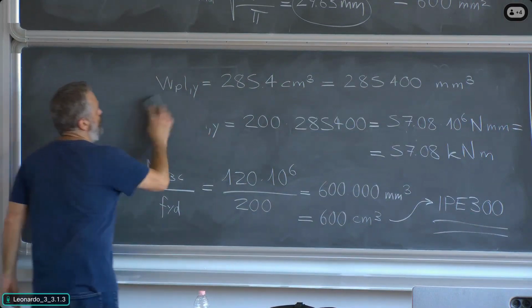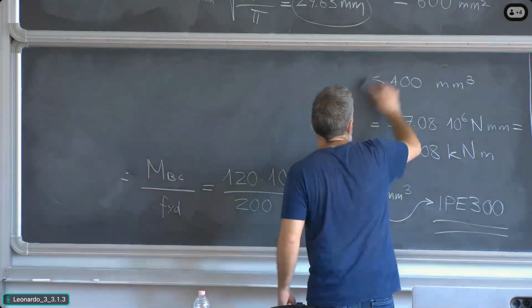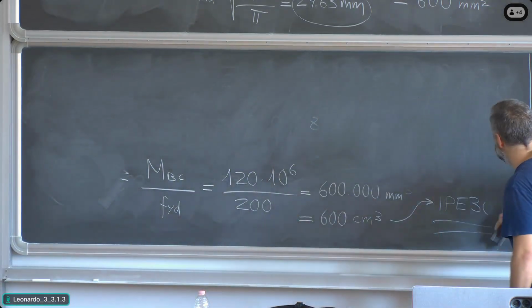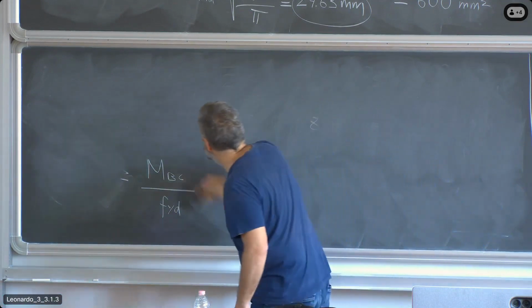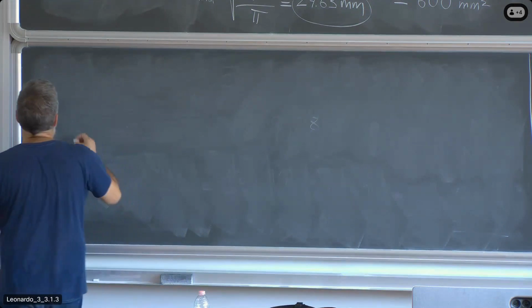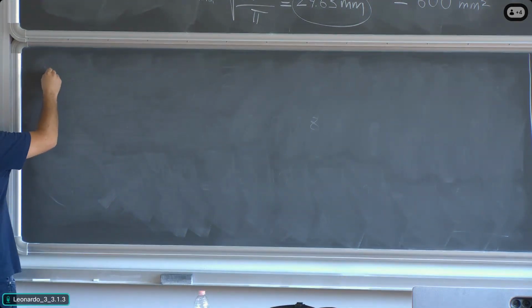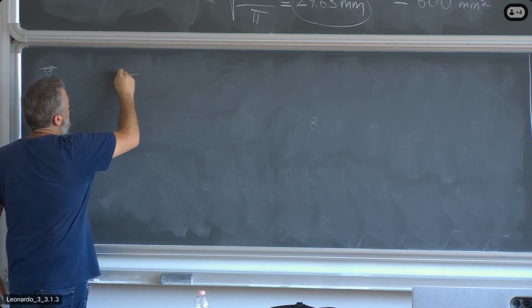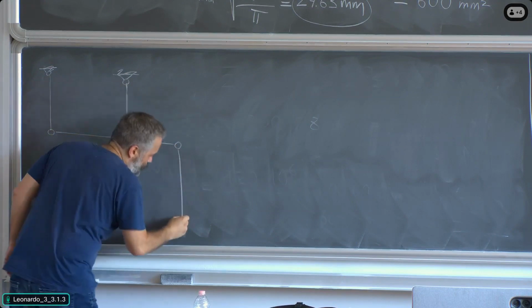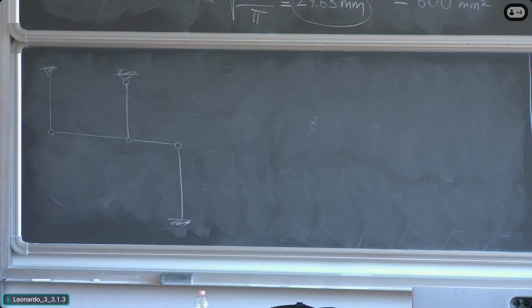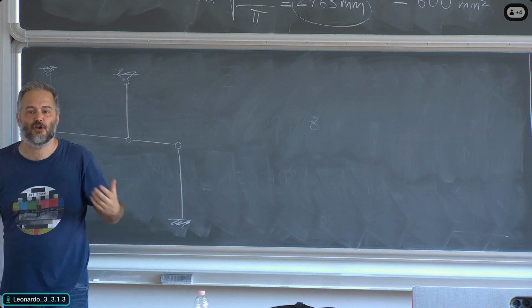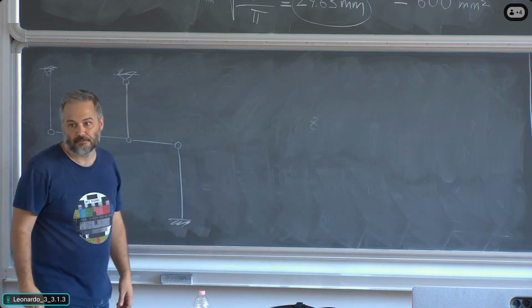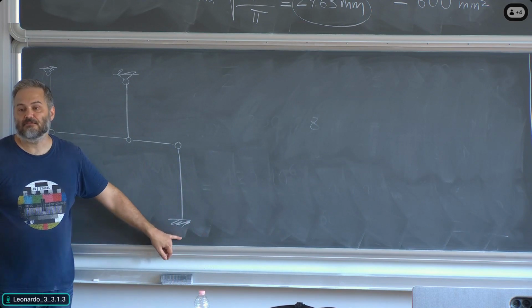This is clearly a problem involving buckling. As a matter of fact, the buckling length is explicitly mentioned. So let's look at the frame we are considering. You know, there is a tie, there is a beam, another beam, and then we have our column with a fixed end. Now, regardless of the loads, we have to ask ourselves how the two ends of the column are restrained. As regards the bottom, there should be no doubts about the fact that it is built in.